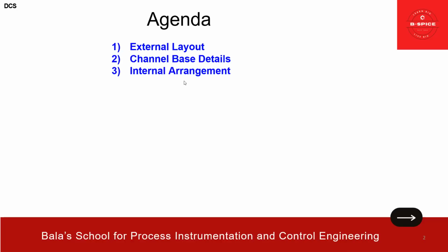Then the internal arrangement: what is going to be mounted internally, meaning your power supply, controller, FCU, FIO, network interface unit, and the terminals, and how you are going to arrange them. That should be the third sheet. Then the fourth one is a sectional view of this internal arrangement, a cut XX and YY.